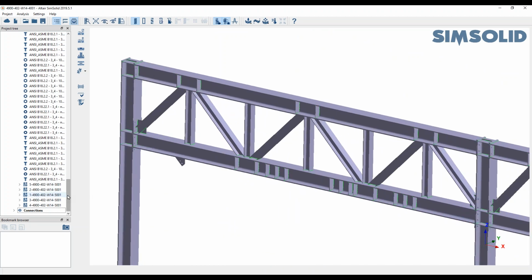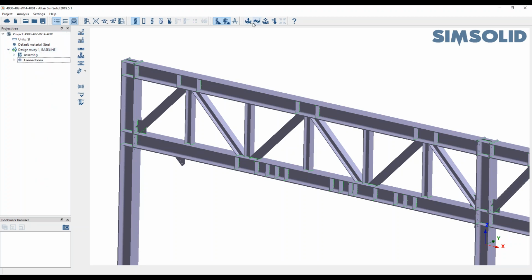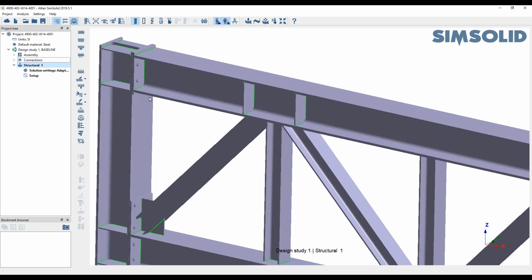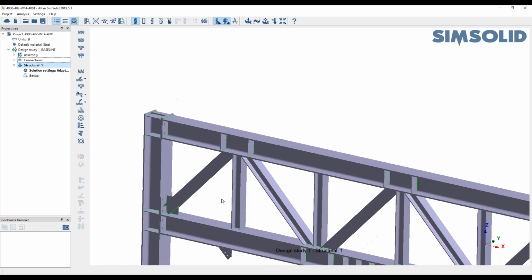I'm going to go and create the stress analysis. So let's just go and create a static linear analysis. So in this example here, I'm going to create a couple of studies, and what's happened here is that everything is bonded. So we're going to run as a bonded analysis, then we'll change the contacts between these plates because in reality they'll be separating or sliding, and you can then basically compare the results.